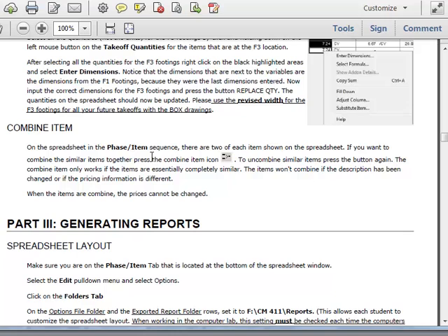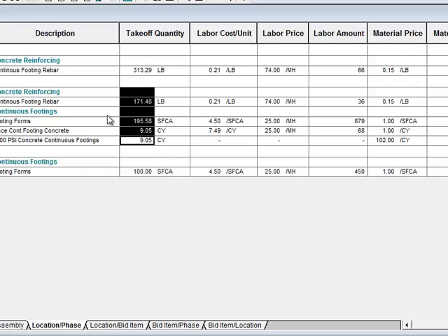And then adding one. That would be if, oh, I just need to add a little bit more. I'm going to add an extra 50 lineal feet. Yeah, you could do that, just for factor of safety. Or another takeoff. Say, oh, I don't want to have to go through that whole thing again. I know it's just these. Change my variable. It's just another way to take off.